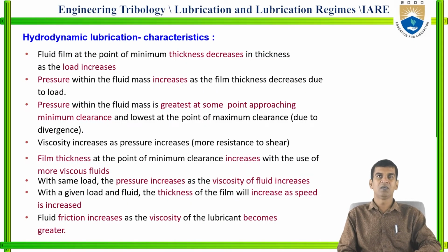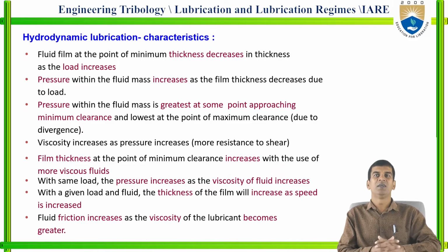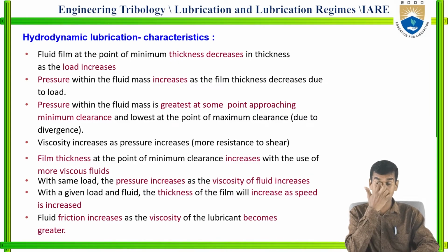Now you can see the hydrodynamic lubrication characteristics. The fluid film thickness at the point of minimum thickness decreases as load increases. If the thickness decreases, the load is increasing. When load is increasing, the thickness will be decreasing.